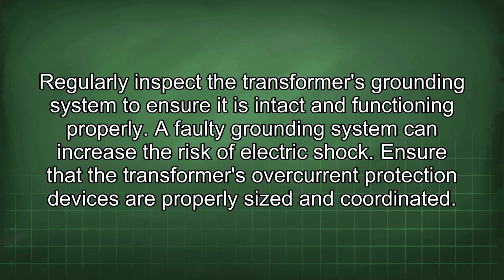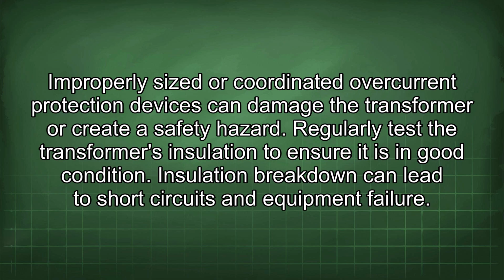Ensure that the transformer's overcurrent protection devices are properly sized and coordinated. Improperly sized or coordinated overcurrent protection devices can damage the transformer or create a safety hazard. Regularly test the transformer's insulation to ensure it is in good condition. Insulation breakdown can lead to short circuits and equipment failure.